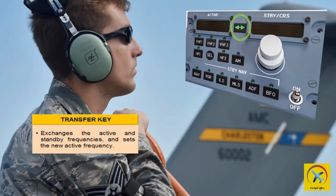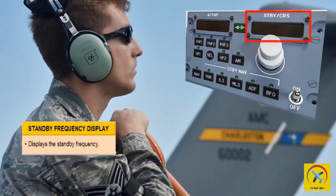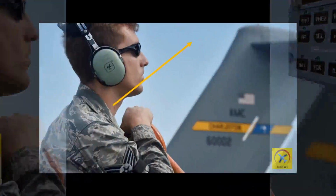Transfer button. The transfer button when pushed, exchanges the active and standby frequencies, and tunes the new active frequency. Standby or CRS frequency display. The standby communication frequency is normally displayed in this window. This frequency is changed by rotating the frequency selector knob and is activated by pushing the transfer button. The CRS is displayed when a navigation radio is remotely tuned. The transfer button when pushed, exchanges the active and standby frequencies, and tunes the new active frequency.